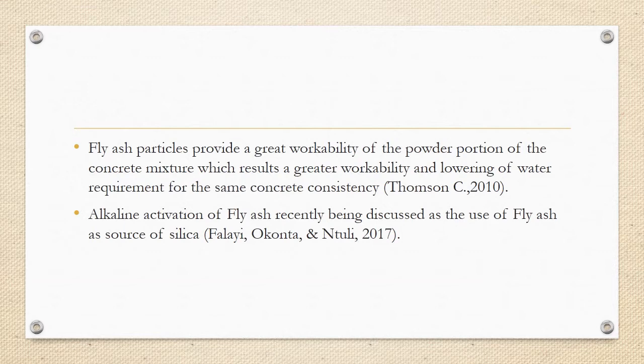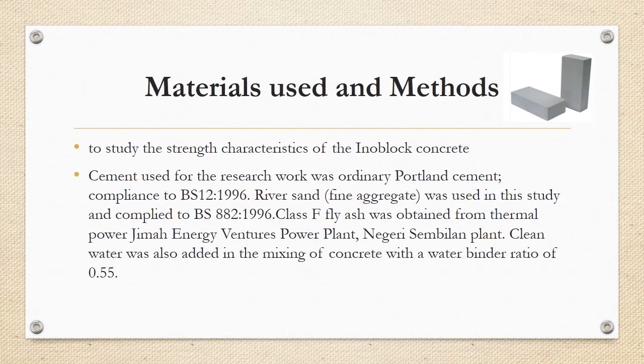Thomas also said and discussed that fly ash particles will provide a great workability of the powder portions of the concrete mixture, which results in greater workability and lowering of water requirement for the same concrete consistency. And recently, alkaline activation of fly ash is being discussed as the use of fly ash as a source of silica.